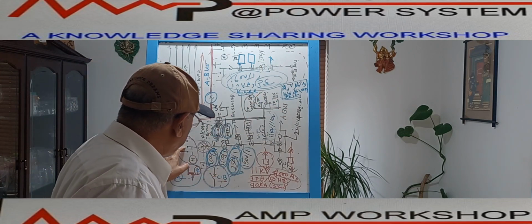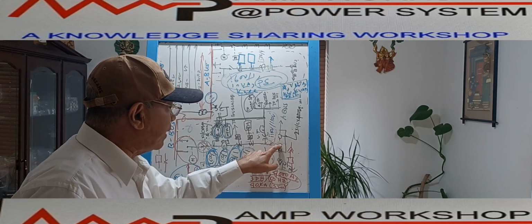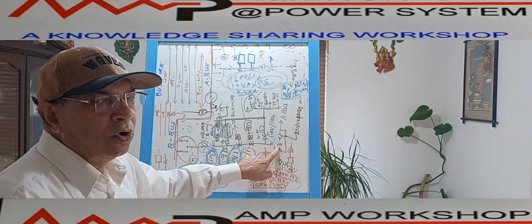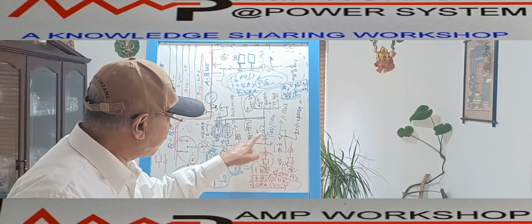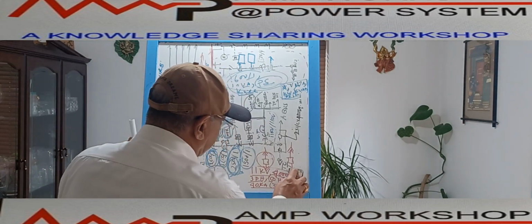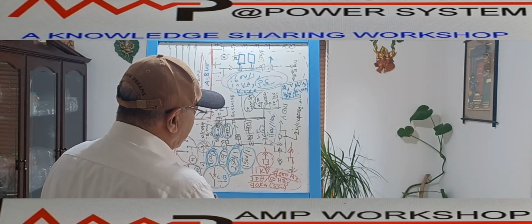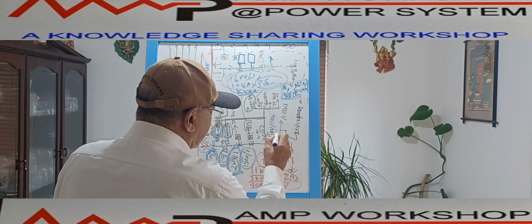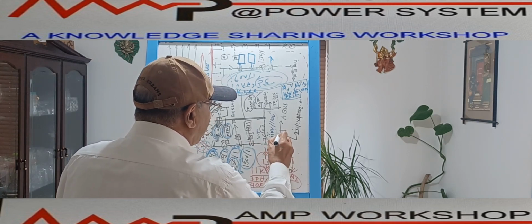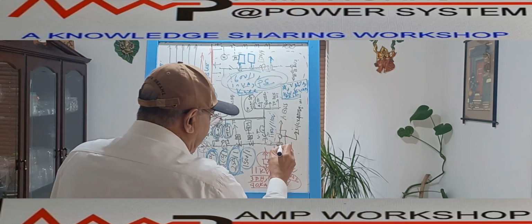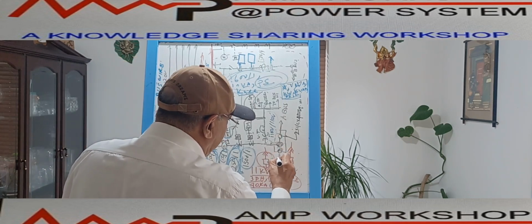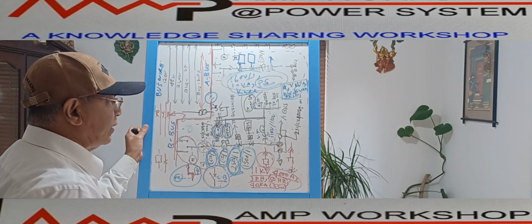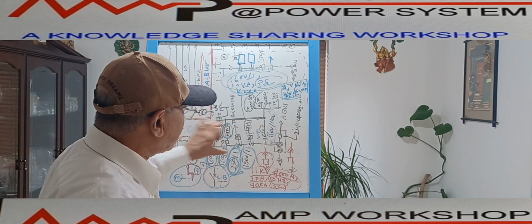And from the bus bar, one bus point is coming over here, and then from this point another point will go to the generator connection. So I am showing over here 2 GT, generator transformer. When this line comes over here, there is one terminal, connected to this bus. Then from here there is a shorting to the other terminal. From here it is going to the A bus, and then it is connected to another terminal. That terminal goes to the generators. The generator part I will draw afterwards, showing how it is connected. Okay, this is the B bus connection details.